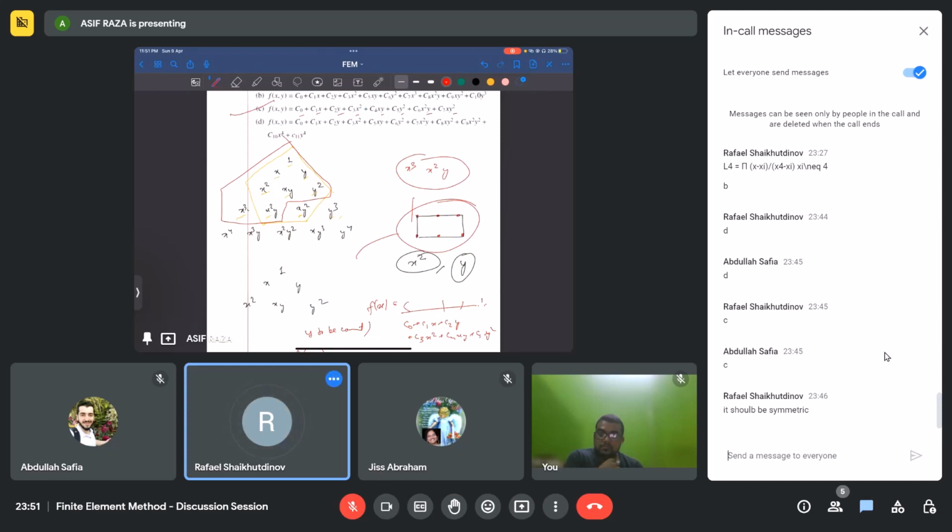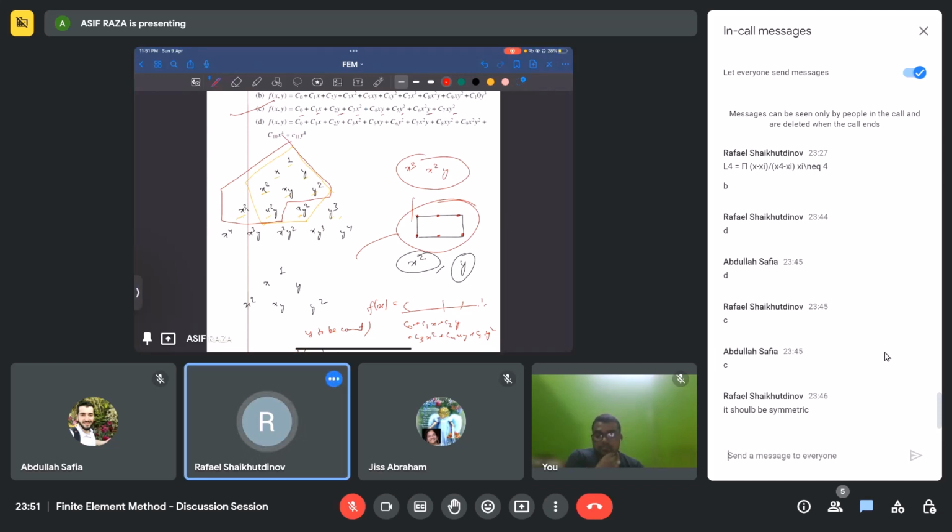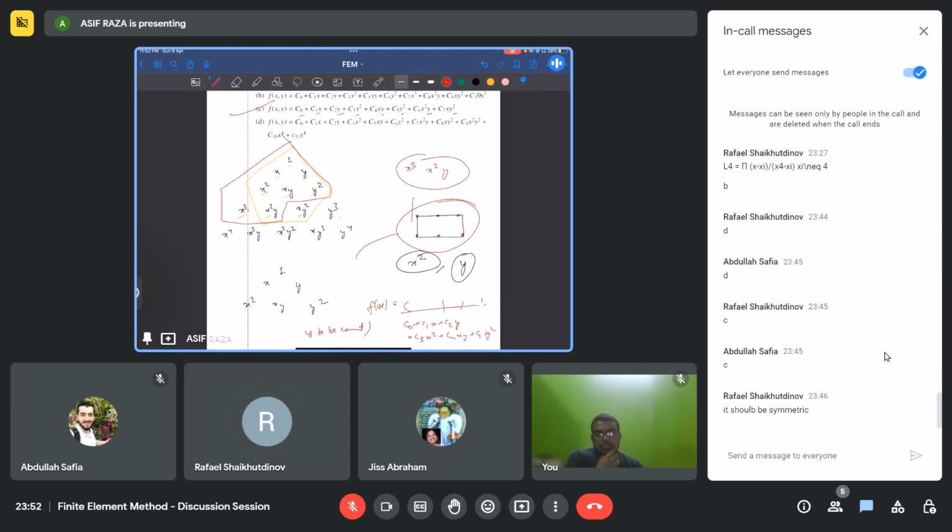If some characteristics require a high order polynomial along x, for instance, boundary elements consist of a distributed load with x square order, if we want to take this with a serendipity element, we can assume asymmetry here. We discussed that in that regard, like how that numerical integration we will use.